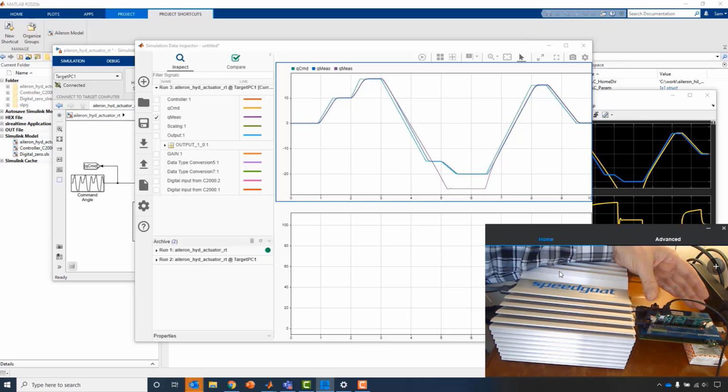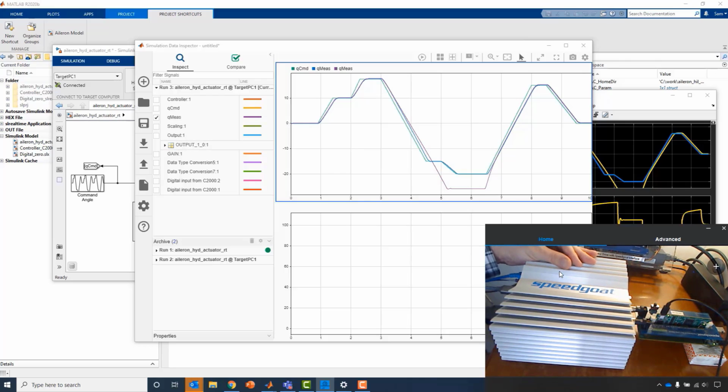And so the hardware in the loop allows you to test the embedded controller with a real-time simulation of the machine or the environment that it would normally be in. So this is connected with the same physical and electrical connections as it would be connected to the real machine. And so it's the closest thing to the real thing as you can get. So it's very valuable as far as risk reduction and testing earlier in the process. All right, thanks. I'll hand it back to you.